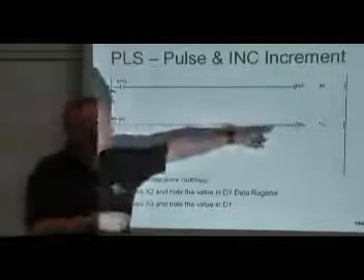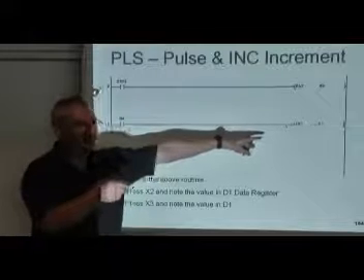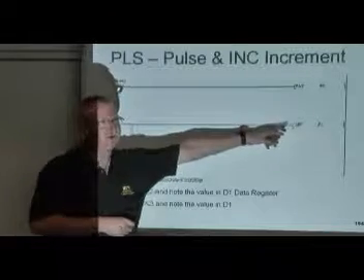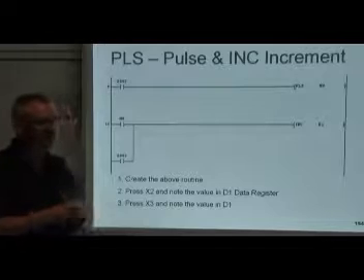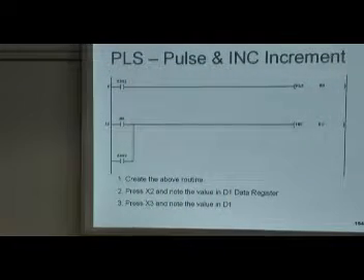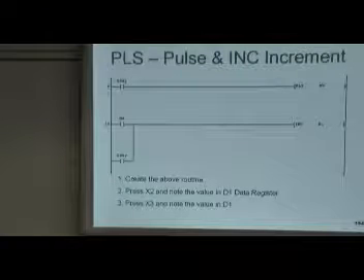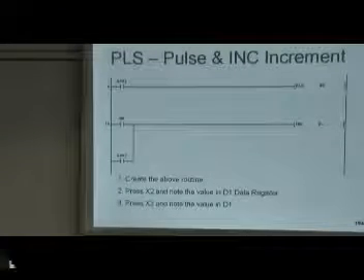Okay, let's go to monitor write mode on your PLC and change INC to INCP, P for Peter. Yeah. So you've got the monitor write mode, which is that one there.